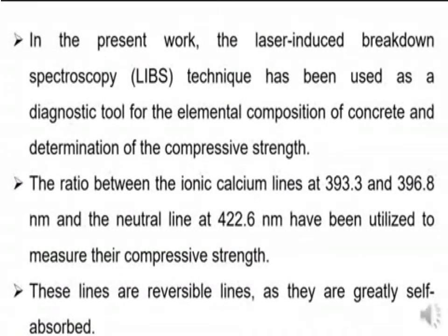In the present work, we want to measure the concrete compressive strength by using the LIBS technique. LIBS is the acronym for laser-induced breakdown spectroscopy, which also measures the elementary composition of the concrete. We will measure the compressive strength of concrete by LIBS using the ratio between the ionic calcium lines at wavelengths 393.3 and 396.8 nanometer and the neutral line at 422.6 nanometer.